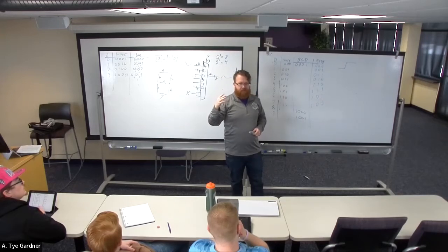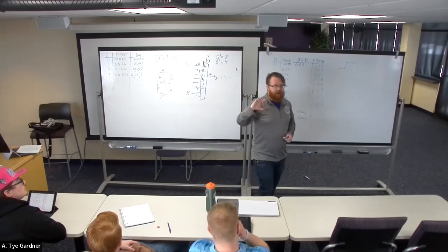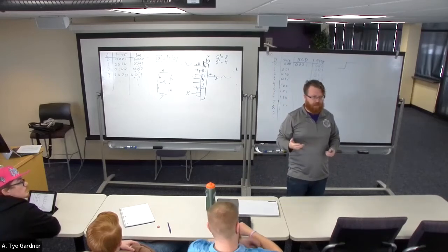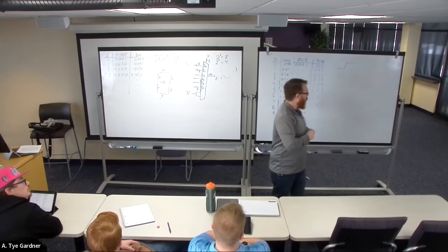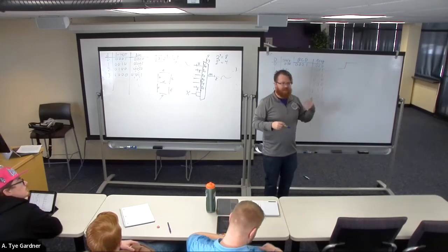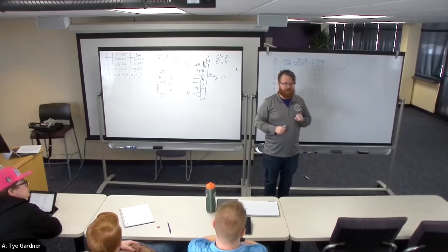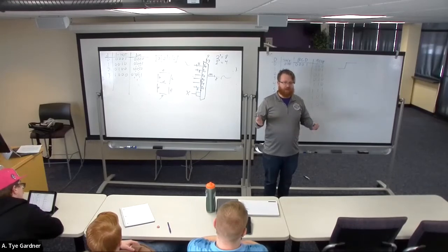In this case I need something like 8 of them, and they're all toggling at the same time. So I get this big transient current that actually ruins the measurements. Whereas if I gray coded it and selected it that way, I only ever had one changing and my currents were never large. In fact, it was always the same level of current and very predictable. That's one real world application of why you would use gray coding.